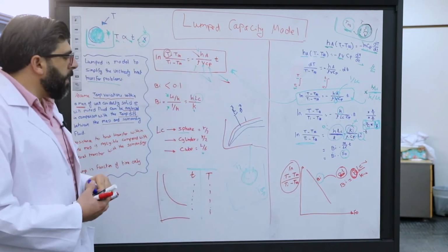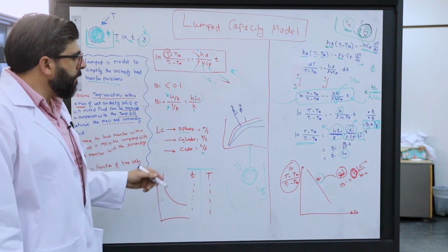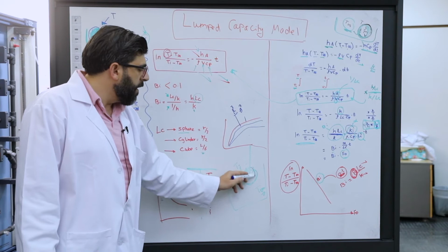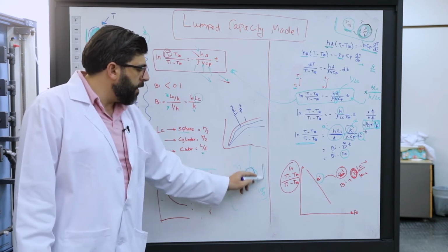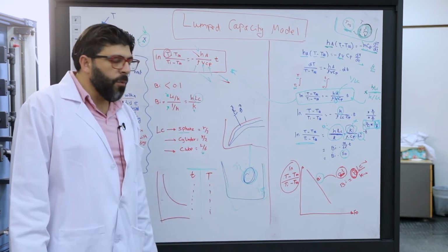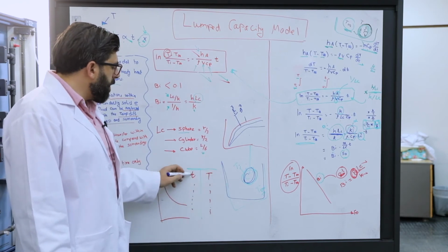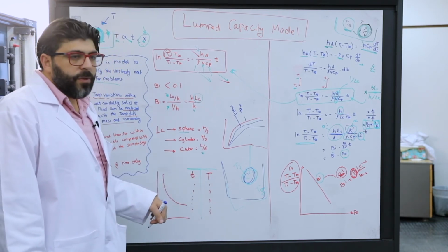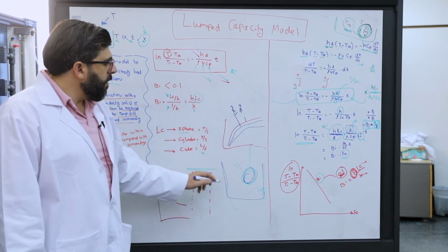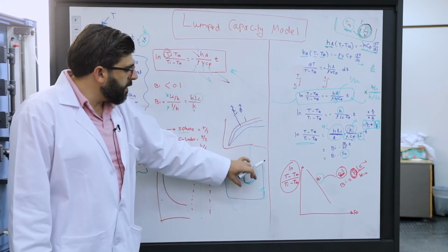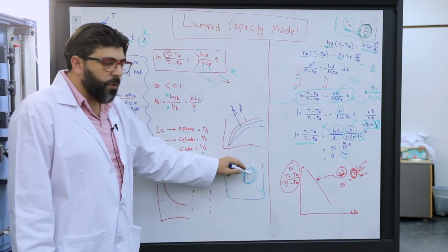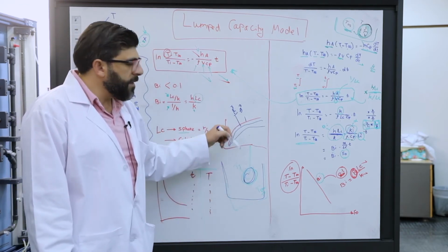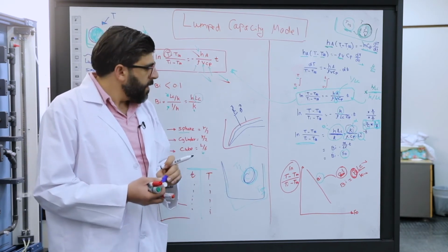We will apply the experiment two times, one for heating and one for cooling. For heating, we will take the sphere at room temperature and put it in hot water and check the time and temperature with the sensors. And then we will do the reverse experiment. The opposite way, we take the sphere from the water and put it in an ice tank, and then find the cooling curve.